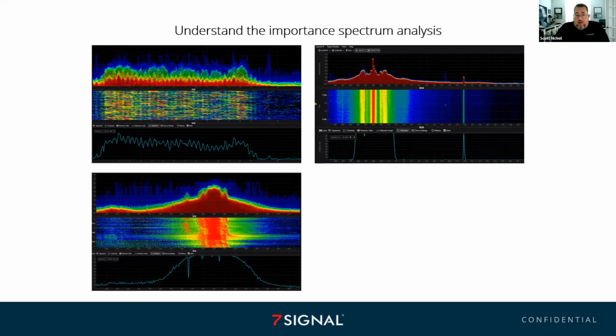Now, this one was really interesting. Again, I was at a big manufacturing facility, and they were having problems in a very specific area. I had several long conversations with, what do I say? Jim Palmer. Jim Palmer, thank you. And Jim was able, by looking at the waterfall graph and its signature, to tell me what that was. I already knew what it was, but he was the only person who figured it out because of his long history in spectrum analysis, and how the signature, especially when you're looking down here and you get these sweeps that kind of come out, this is microwave related, and that was the magnetron sweeping the signal out.